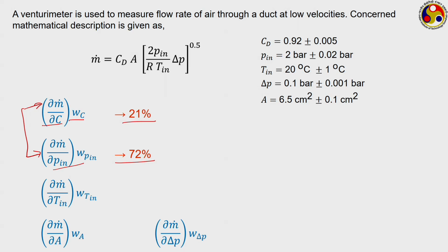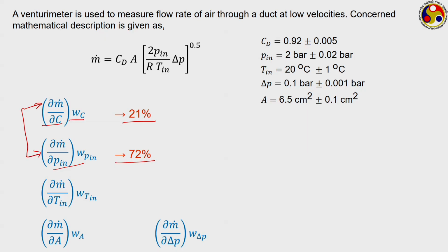So that provides us a way of tackling or choosing our instrument. Like in the previous example, you have seen a way of identifying the measurement method. Although we have to measure 2 quantities, it is better to go for both voltage and current measurement instead of only voltage measurement or only current measurement. Whereas in this particular case, there are 5 quantities with some uncertainty, but instead of trying to improve all 5, if we look at reducing the uncertainty in only this particular quantity, then we are going to get the largest gain in the final output.